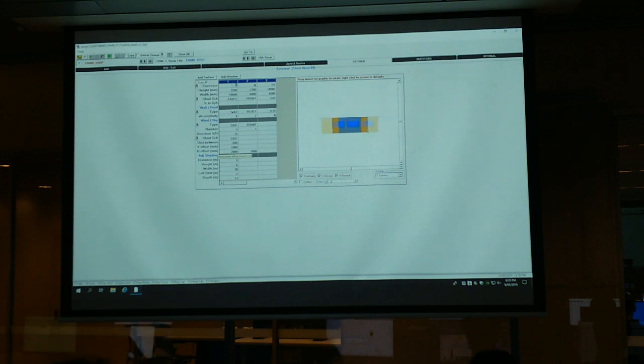For this wall, that's the vertical side offset from the window, 1000 millimeters. If we change the number, you can see that's too big. Then you can see the location changed.